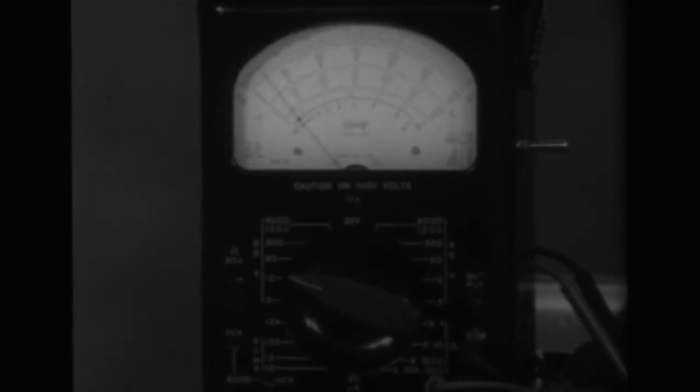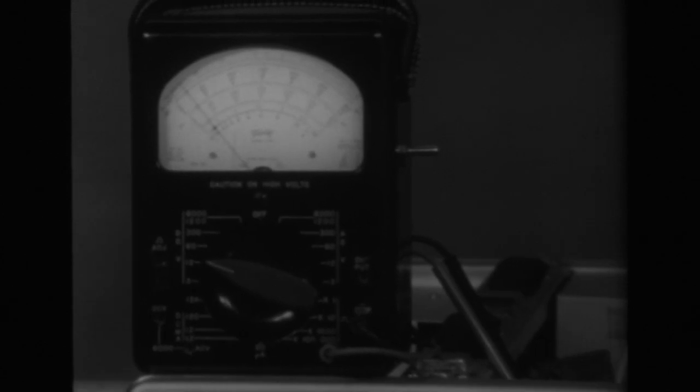Now, lest you become confused, let me point out that sometimes we carelessly say gas current, and it happens that gas current would be equally distributed between the two halves of a twin triode tube. But it is possible for grid current to exist in one half of the tube which does not exist in the other half. For that reason, we have to check both grids of the input trigger amplifier tube. Now, watching the meter, we saw that there was very little shift as far as this grid is concerned, certainly less than 1 scale division on the meter.